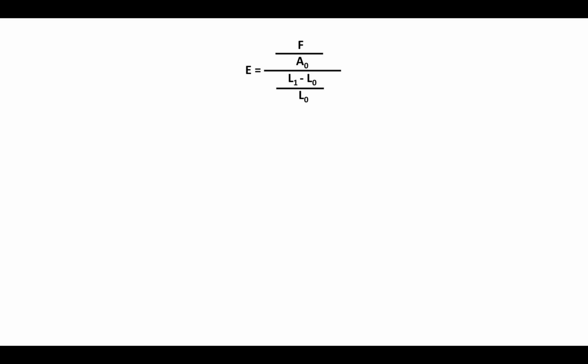Experimentally, I should be able to calculate the elastic modulus of a spoke material, because if I know the force that I'm putting on the spoke, and I measure its starting cross-sectional area, if I measure the length of the spoke or the percentage increase in the length of the spoke, then I can calculate the elastic modulus. Conversely, if I already know the elastic modulus, I can calculate the percentage increase in length that I should expect from applying a given force.